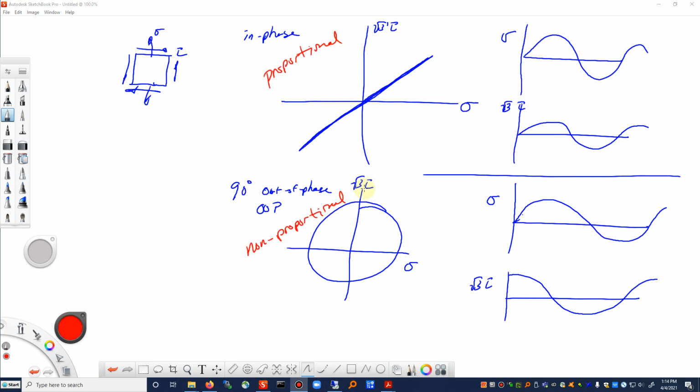So once you get used to looking at phase plots, they can really convey a lot of information in a compact way. So we have a proportional loading in the first path, and if it's 45 degrees on those axes, then you have equal amounts of sigma and tau contribution to the equivalent stress. If you start changing the angle away from 45 degrees, then you have more contributions of sigma or tau respectively as that line tilts up or down.